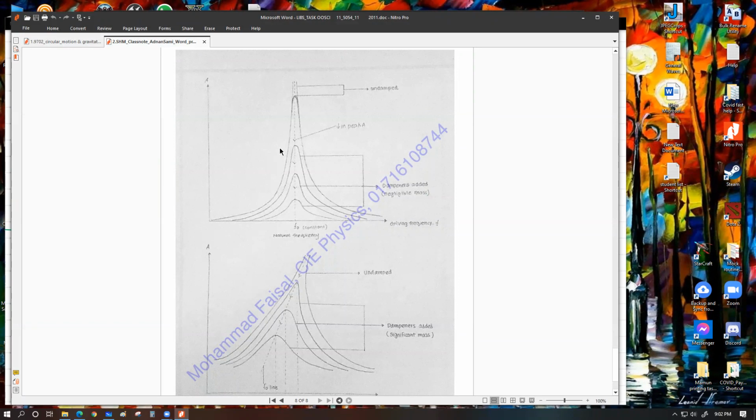What is very important for you to understand is that mass is the key factor that controls most objects' natural frequency. More massive objects have lower natural frequency. They have more inertia, so they tend to move slowly, with more lethargic or inertial resistance, and lighter objects tend to move faster. So this is a scenario where the mass of the system either remains absolutely unchanged, or the change of mass because of the addition of a damping mechanism is considered negligible.